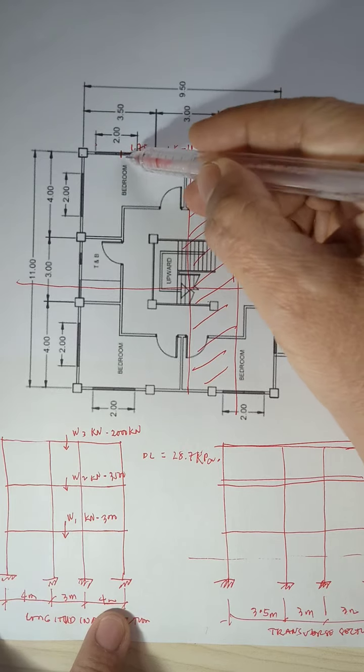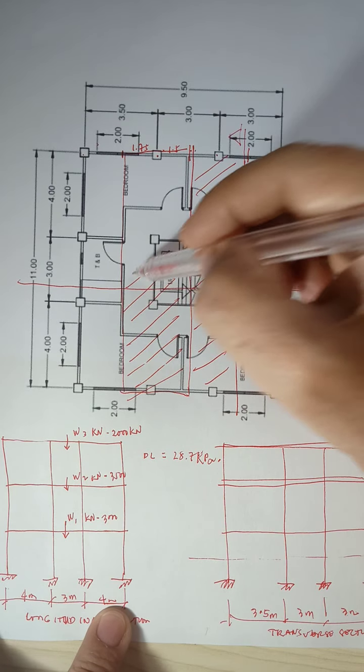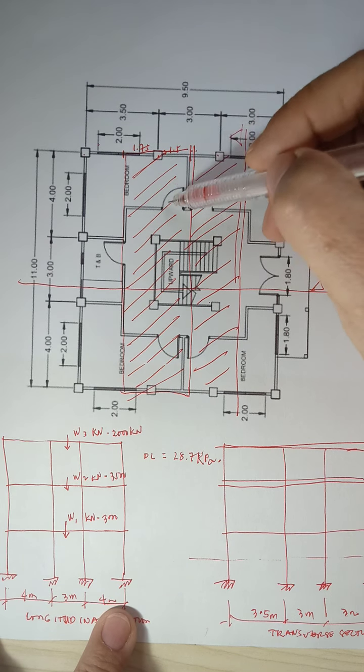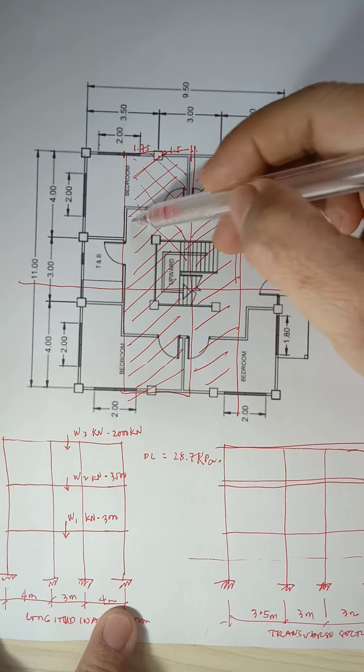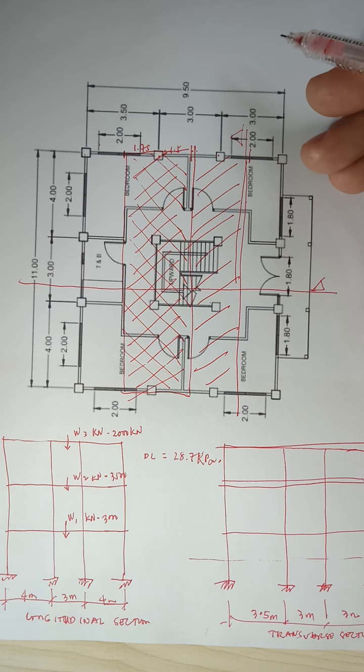So this one has the bigger tributary area, and this is what we will design for, so that the beams we design are bigger. If you use that for the other frames, they can carry the load since they are designed for a bigger load. The other frame with the smaller load would still be adequate. So this total dimension will be equal to 1.75 plus 1.5, that is 3.25 meters.